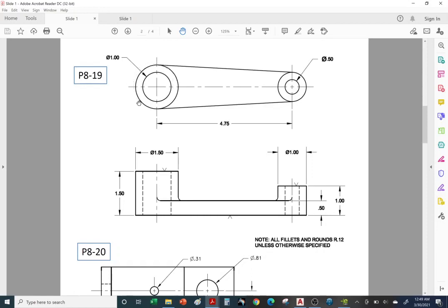The large circle is a solid. It's the shaft, right? Same thing with this one. So the large circles are shafts, so you do not dimension the circles, you dimension the rectangular view, right? This large circle here is 1 inch in diameter, but you have to put the dimension here because this large circle is a solid. Same thing with this circle. It represents a shaft, a solid. So here is its diameter of 150.